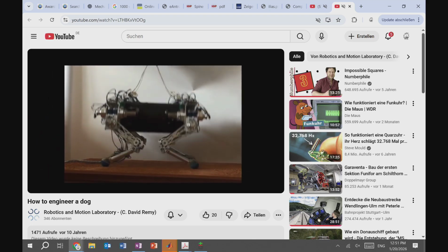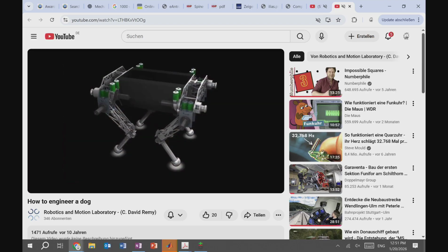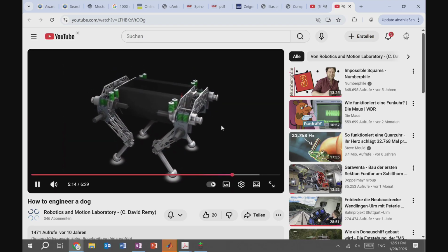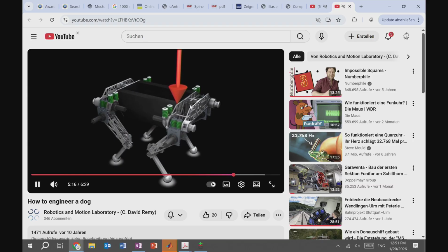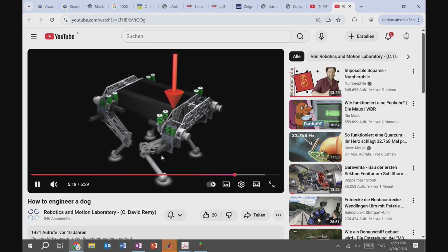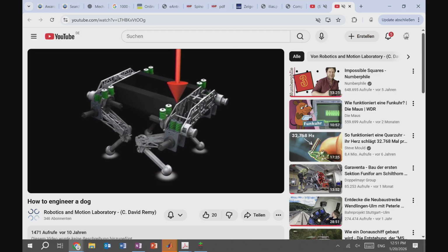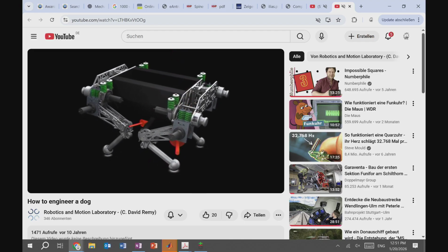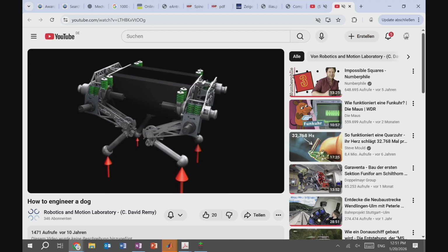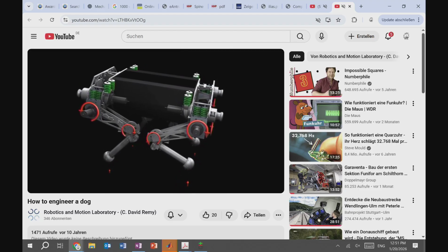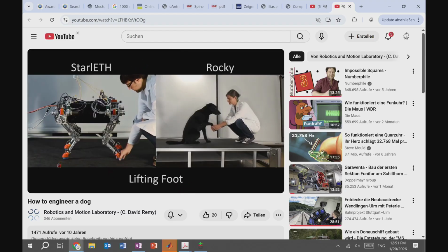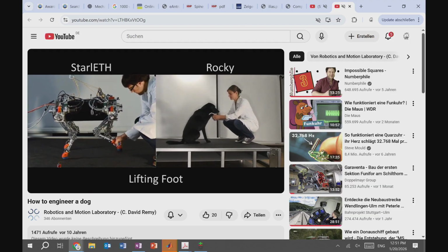And these virtual forces, in this case mostly damping forces, are distributed from the main body onto the individual joints. And that's our Jacobian transpose mapping. This is exactly this projection that we talked about: take these forces, distribute them into the generalized coordinates. That's J lambda transpose times whatever force we had.